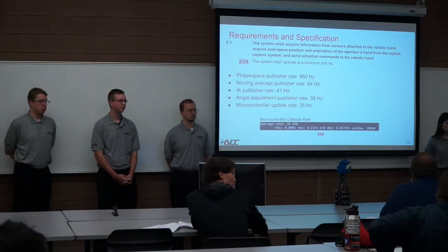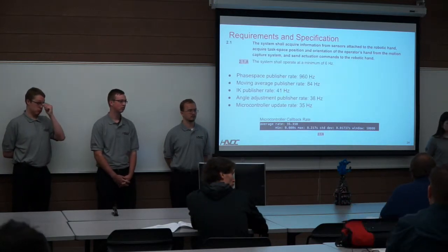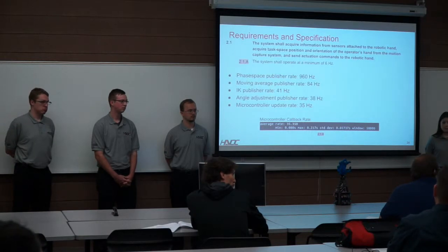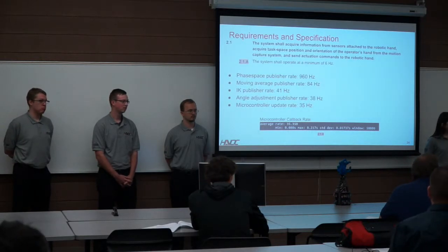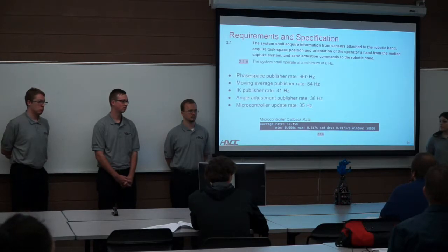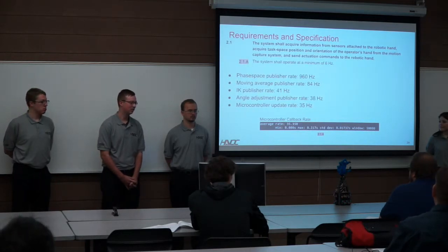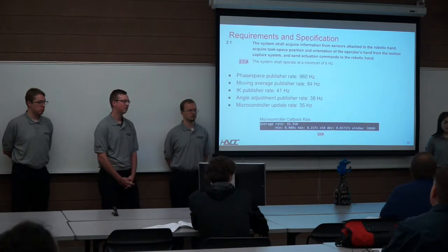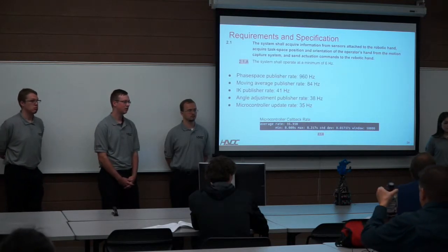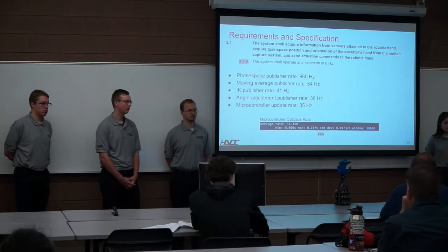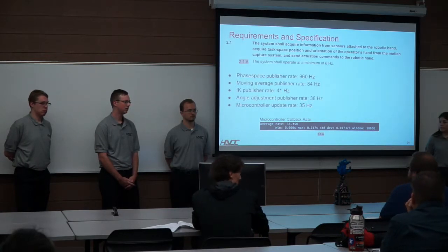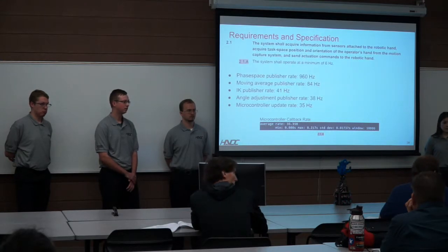Follow on that question then. Looking at this mechanical system, what is the bandwidth of that system? I'm asking so that I know how rapidly I should sample the output of this system and not do harm, for example, aliasing. Can you rephrase that? So you built a system. Yeah. Do you have an idea what the highest frequency the system can respond to, so that when I decide I want to look at the system with a computer and sample the output, I know how fast to sample it?